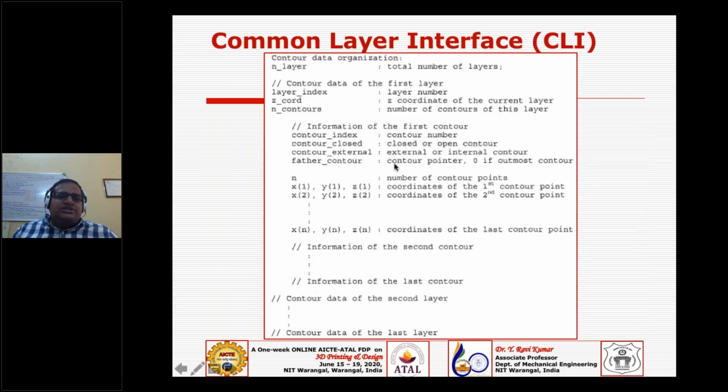And then you generate a G code or .cli, I'm calling. And again, the worst part here is you don't have a standardized data format. STL is the standard for the mesh file, but there is no standard file like G code. G code is only for maybe the FDM machine, and now it is open source.